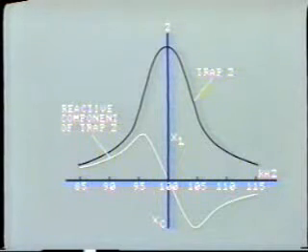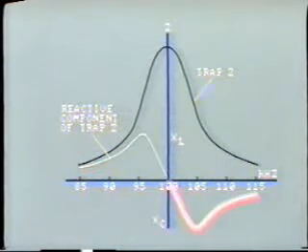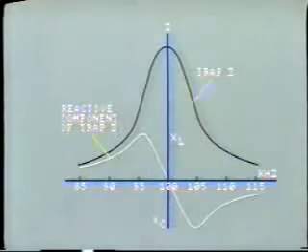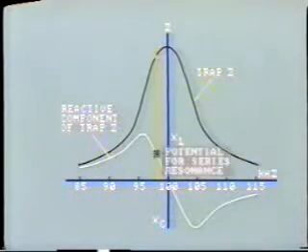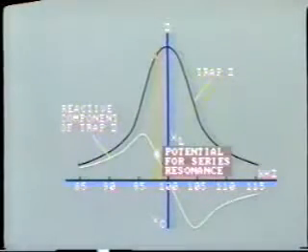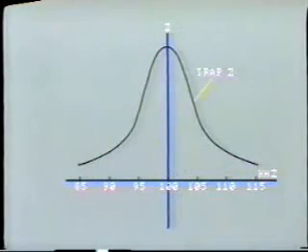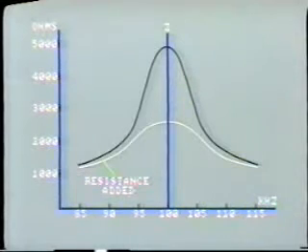of the wave trap will be disturbed, and it will become inductive or capacitive. From this curve, we can see that a small frequency change from 100 to 98 kilohertz will produce a highly inductive component with the consequent potential for series resonance with bus equipment. In order to avoid this potential problem, further resistance is added to the line trap.